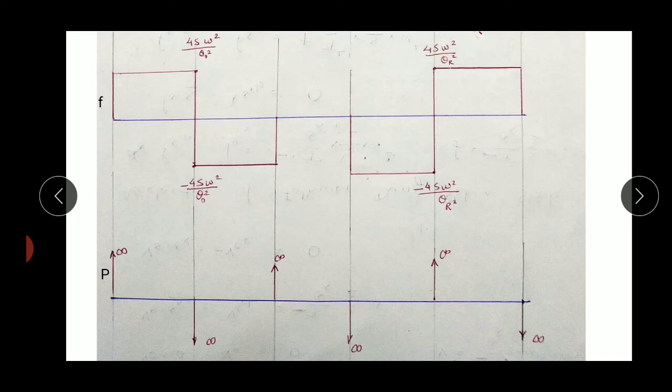In between the start to the middle of the outstroke, as it is a horizontal line, and a horizontal line has zero slope, we don't have any jerk between the start of the outstroke till the middle of the outstroke, but infinite jerk at the start of the outstroke and in the middle of the outstroke.